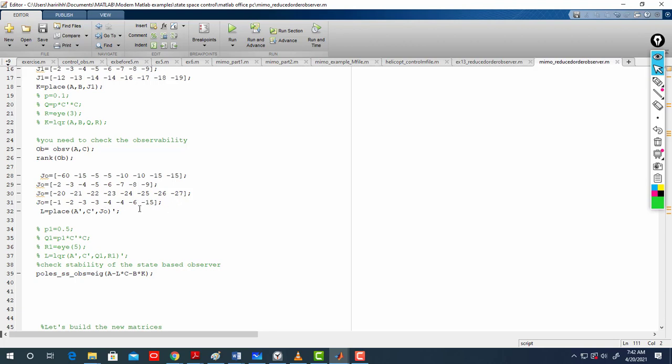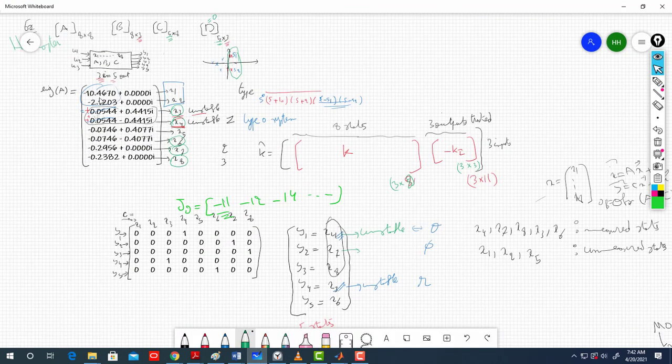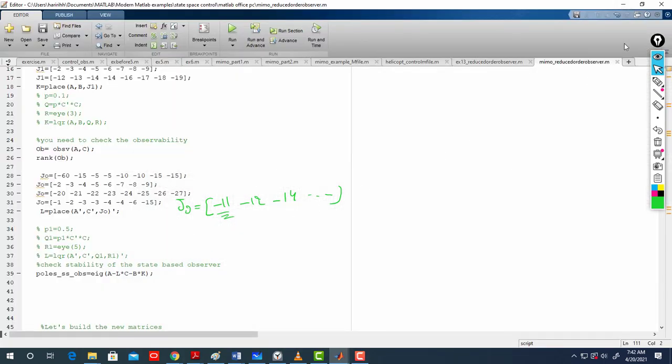We usually recommend, if you want a good design for GO, starting at -11 maybe, and because you have 8, then -12, -13, up to having 8 of them. Why -11? Because the eigenvalues of A start at -10 something, you see -10.4, so then start at -11.